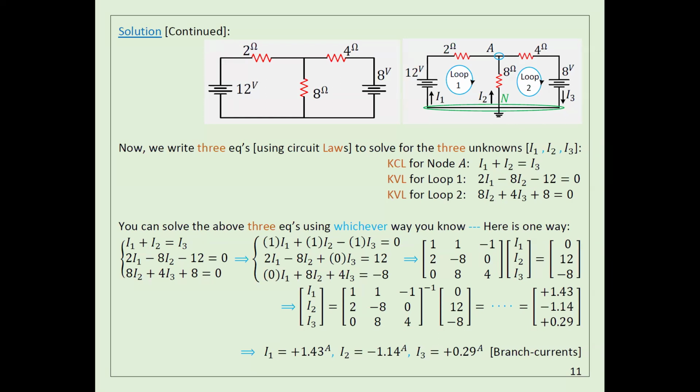Any questions? So all what I did, guys, very simple: I applied Ohm's law, Kirchhoff current law and Kirchhoff voltage law in order to get 3 equations. In these 3 equations, I have 3 unknowns, which are the currents I1, I2, I3. If I can get I1, I2, I3, it's very easy to calculate the voltage here, and then I am done. I found everything. You got what I'm saying? So if I can find the 3 currents here, I can easily calculate the voltage here using Ohm's law.